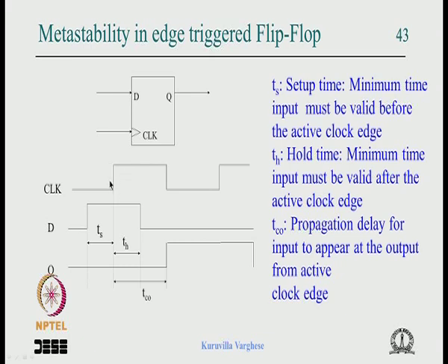When the positive clock edge comes, the slave gets the copy of the master, the slave is enabled, the master is disabled. The time for the slave to set is the propagation delay. Normally again there will be an inverter, and that delay has to be added to the slave latch delay for the propagation delay. So that is the essence of setup, hold and propagation delay.